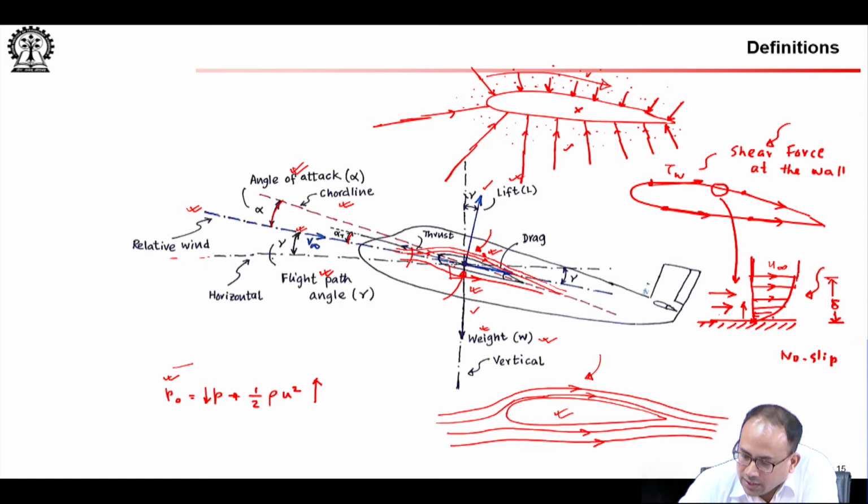So, essentially velocity goes from 0, keeps on increasing to the free stream value, but it takes forever because it reaches the free stream value asymptotically. But so, we define boundary layer thickness as that distance where the velocity has gone up to 95% of the free stream velocity. So, if this is delta, then u here is 0.95 times u infinity. Okay. So, that is how we define boundary layer, and in the boundary layer you see there is a velocity gradient. Your u is 0 here and u goes to u infinity here.